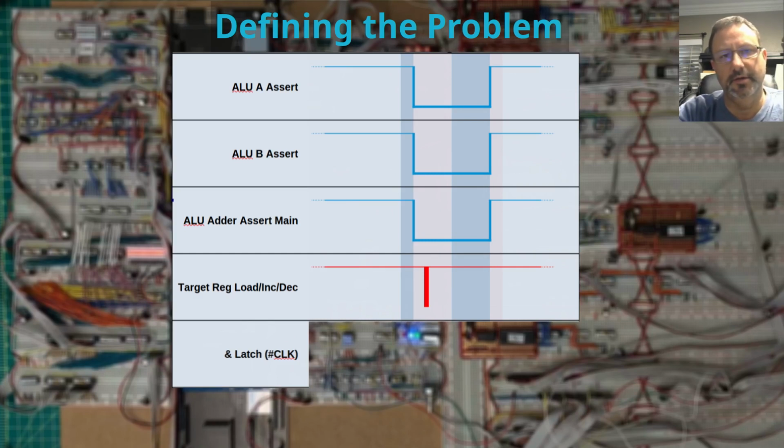And so it's typically a high signal which goes low and then returns high. The load signal itself is an active low signal. And since it's an active low signal, if anything happens to change while that signal is low, the register itself will update its contents. It does not have a single event latch that takes place. Now, this is on the counter ICs. This isn't the latch register IC.